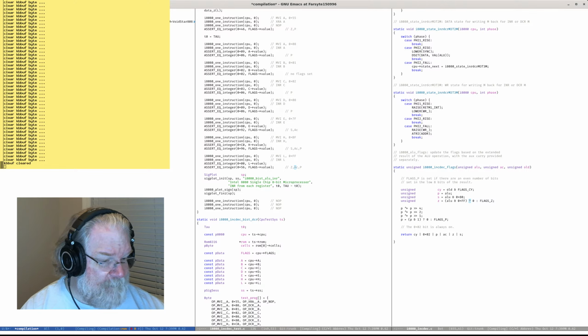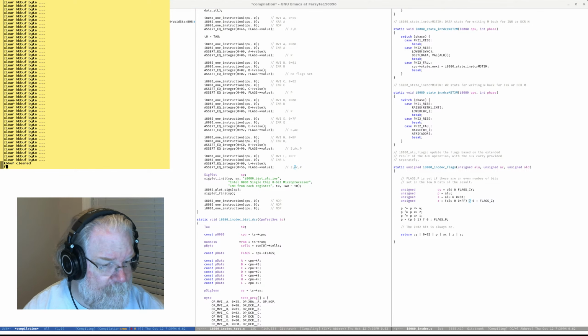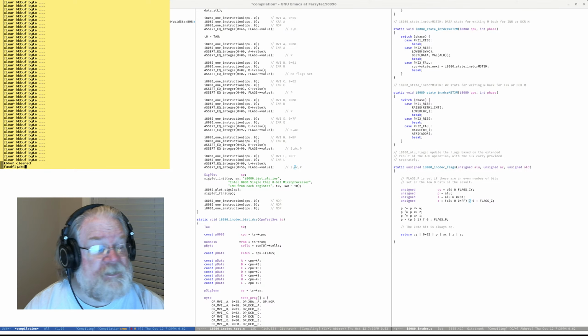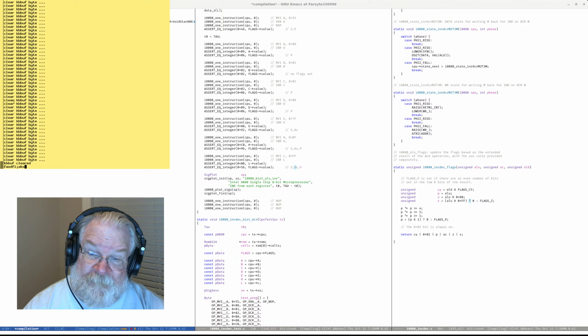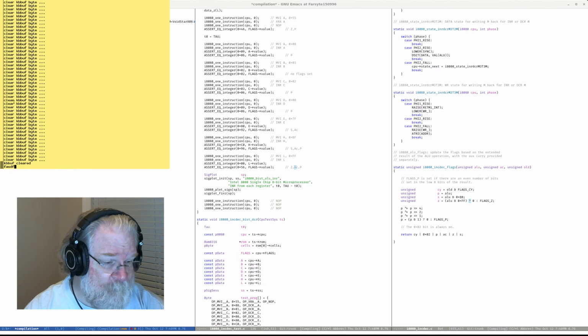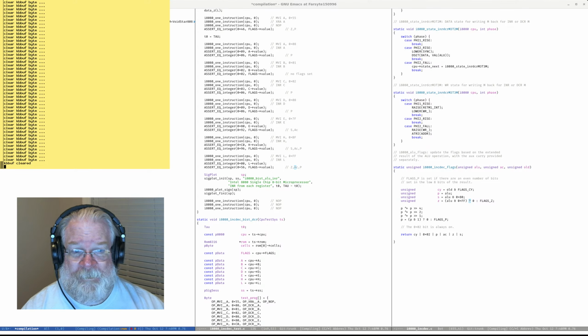Okay, and now we get this KB buff cleared down here. And I've got my text buffer, and I have my backspaces working. Now that's actually explicitly handled in the monitor code. You have to recognize the backspace, you have to send backspace, space, backspace, and you have to zero out the value in your keyboard buffer. And if I hit return there, it does that, and we're good.